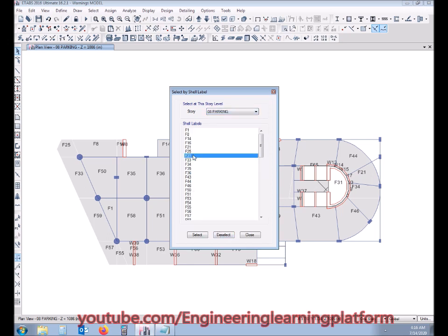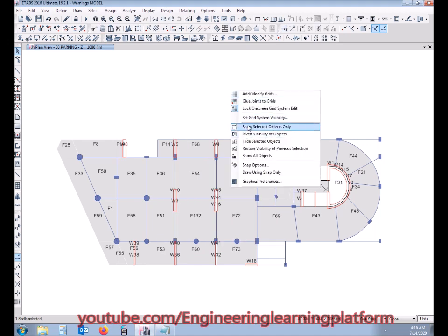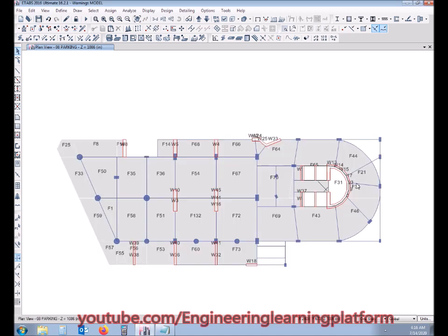So F31 is available here in the void area. As you can see, the opening is being merged here, so we have to fix it. One important thing you might notice is that I am merging the cells although there is a beam, but to deal with that, I'll auto mesh the shell using beams here in the next step. So now we have removed most of the errors.